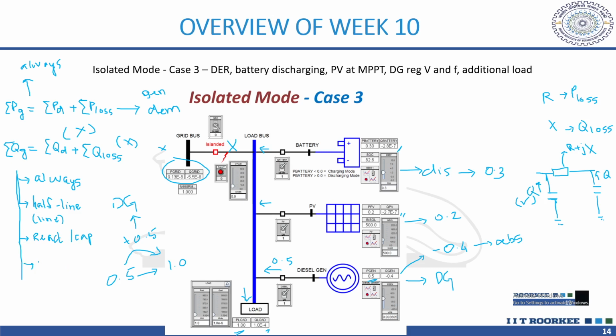Then the status of these transformers, if you remember, the on-load tap changing transformers, their status also affects this Q. So for these reasons, this Q balance is not as straightforward as P. It will always depend upon the loading condition, the line parameters, and the system components, like the OLTC and the shunt reactors and capacitors that we have.